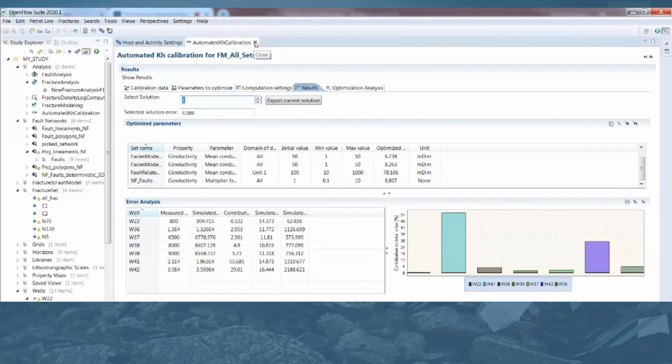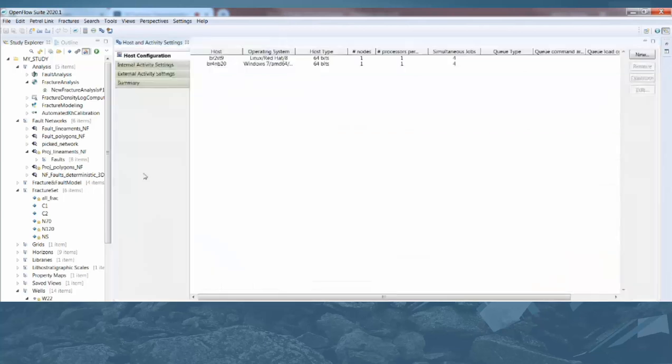So this is exactly the same model as the one you built in the fracture modeling, except that the conductivities have been updated, calibrated. You're supposed to modify the aperture then with Poiseuille's law, and then you can switch to the upscaling part. The upscaling is the last step of the workflow.